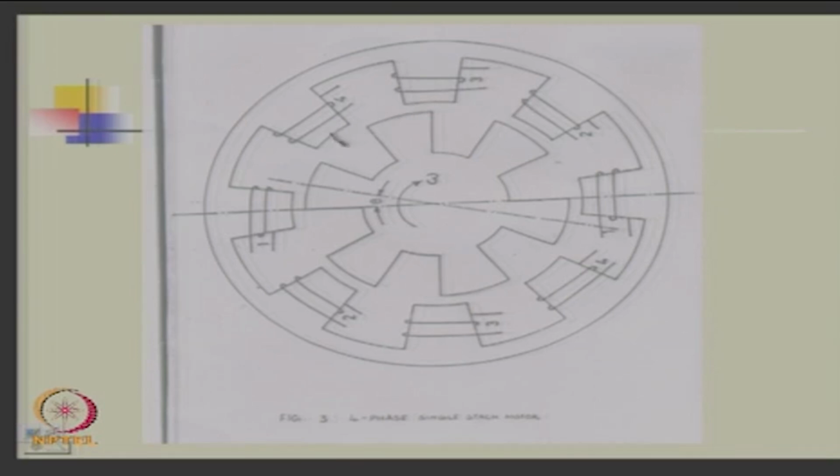In this air gap there will be energy stored, and the energy stored with reference to rotor position is the torque, okay. We have already said the inductance of this coil is maximum and of this coil is minimum at this position. If you pass a current through this, inductance will vary because of saturation here, because this is highly saturated, it being totally an iron piece with very limited air.